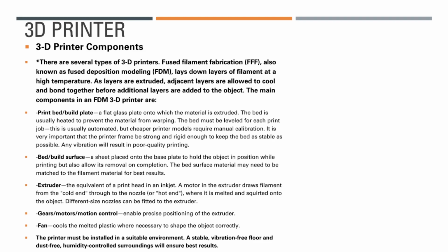The bed must be leveled for each print job. This is usually automated, but cheaper print models require manual calibration. It is very important that the printer frame be strong and rigid enough to keep the bed as stable as possible. Any vibration will result in poor quality printing.